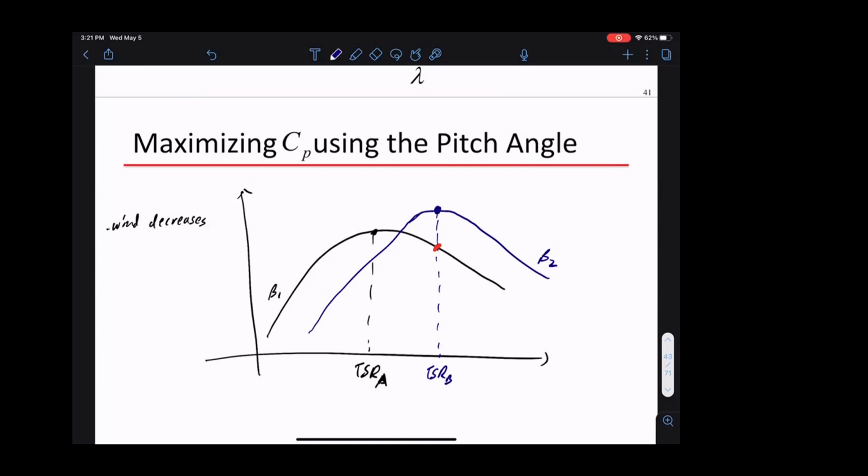And two, what I'm drawing here is a vastly simplified picture, right? In practice, we don't have one turbine, we have one farm. So you changing your pitch may cause a turbine that's, let's say, 100 meters away to suddenly experience some different wind. So they may change their pitch. And you have one farm, so what we care about is maximizing the power coming out of this farm. That can be a complicated nonlinear problem, so the algorithm is not easy. But the sensors, the mechanical parts, the controllers, all that is pretty easy and not very expensive. This is more about whether your algorithm makes sense, not whether you can build a sensor.